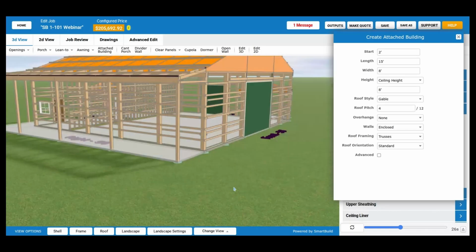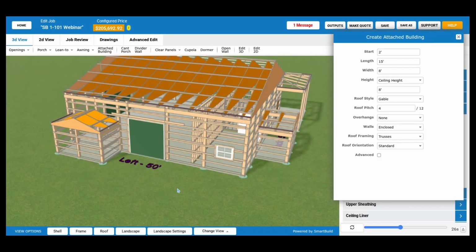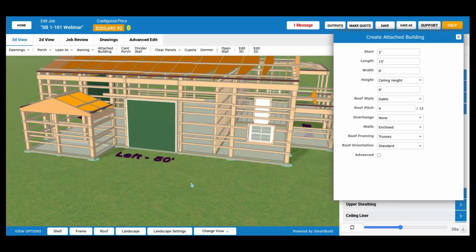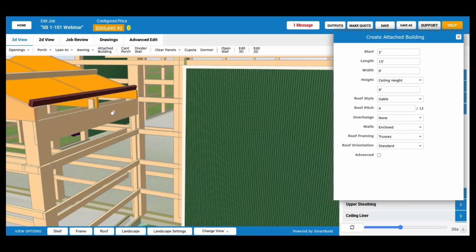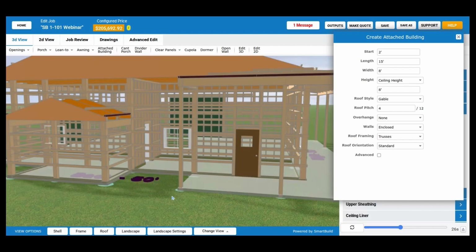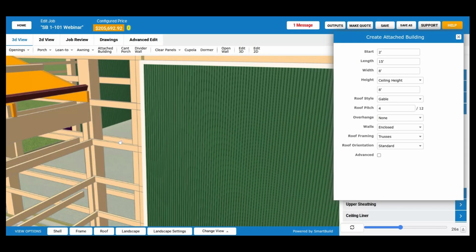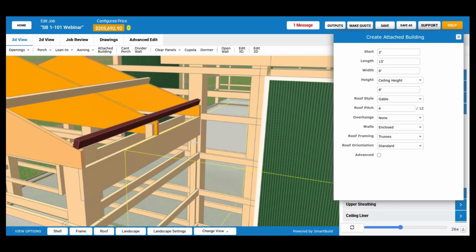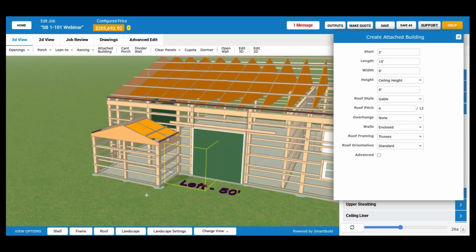Primarily because something has got to hold up the end of that truss carrier that's holding up the trusses that are holding up the roof of that attached building. So those truss carriers, they're held up by that post in the main building. Oh, fair enough. You're talking about these truss carriers? Okay. Yeah, I believe that's the intent. As I'm looking at it, it looks like there's a girt on that wall, just like you would have on a shed. Yeah, that makes sense. It's holding back the interior girts to make room for that.